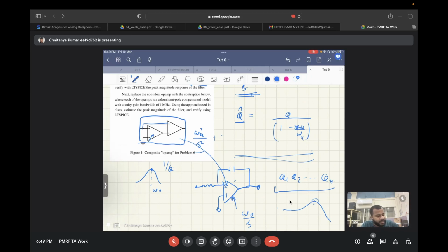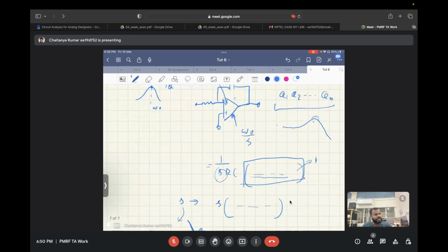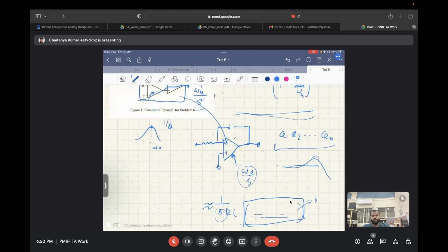This happens because there is a cascade of two op amps, so at least in the frequency of interest, the overall gain that the op amp can give has increased. The integrator's transfer function is then nearly equal to the ideal one. Hence, there will be no quality factor distortion, and you won't see the peaking that you saw with only omega u by s.